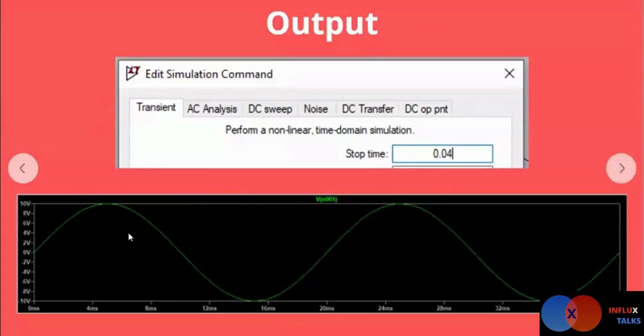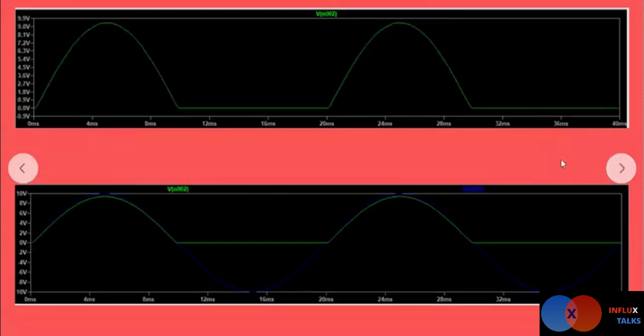Once you click on the wire above the source, you can see a red color marker that comes up. That should be your voltage probe. When you click on a wire just above the source, as expected, you can see 2 cycles of the input waveform. It's a sinusoidal waveform with 50 hertz frequency and an amplitude of 10 volt. Now if I do the same with the voltage probe on the wire next to the diode, you can see that as the diode will be forward biased only in the positive cycle, you will get the outputs as only the positive cycles. And the voltage won't be exactly 10 volt. There might be around 500 millivolt difference, probably due to the diode.